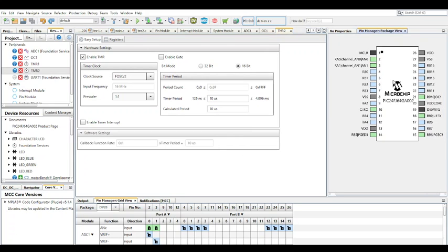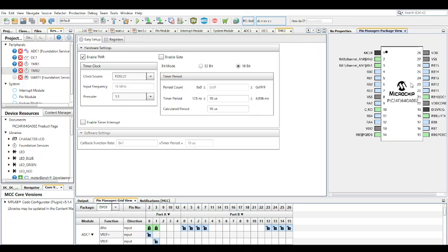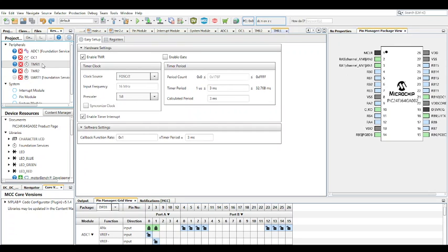And in the real world application, if you're not doing it on a professional PCB, like a PCB where there's a solder mask on it, and the PCB is not acting like a giant antenna, you could make the loop a lot faster than this. Now in this case it's 3 milliseconds, but if you have a real professional PCB, you could take this down to 200 microseconds.